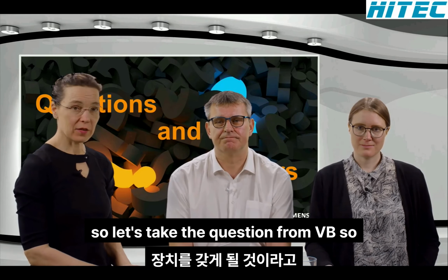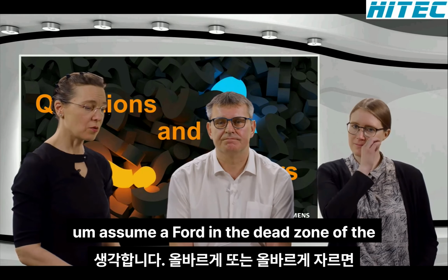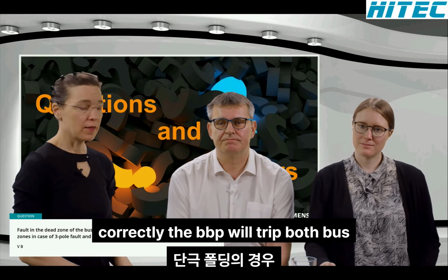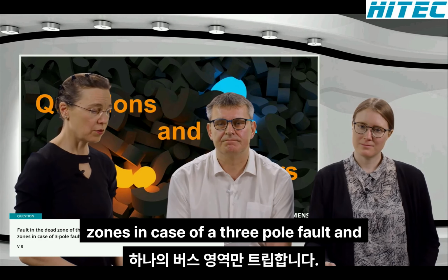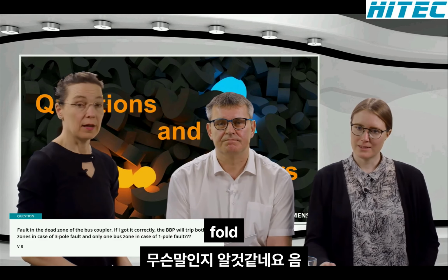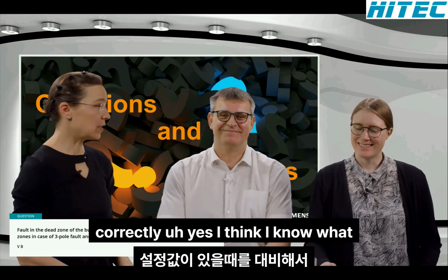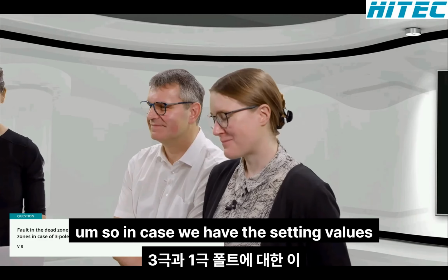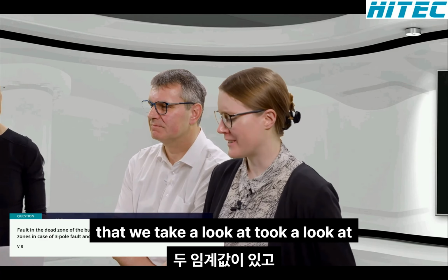So let's take the question from VB. Assume a fault in the dead zone of the bus coupler. If VB got it correctly, the BBP will trip both bus zones in case of a 3-pole fault and only one bus zone in case of a 1-pole fault. Is this understood correctly? Yes, I think I know what is meant. Perfect. So in case we have these setting values that we took a look at earlier.